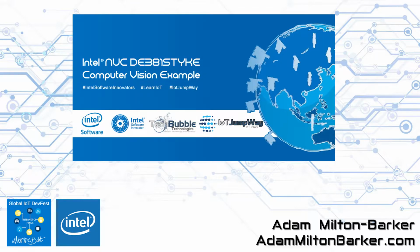For the fifth solution, the server used for the AI was rehomed onto an Intel NUC, which was kindly provided by Intel. The structure of the network also changed. The program that handled the facial recognition and identification would now connect to multiple IP cameras. Previously, the camera devices would send the frames through MQTT to the broker, which would then forward them to the local server. With this move, the identification process is more efficient, and also the camera devices only need to stream video. They do not need to connect to the communication broker, so third-party devices are now supported.